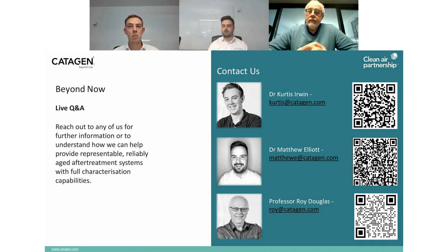So I think the physical emulation and the virtual simulation tool set actually go very, very well hand in hand. And I think we can effectively utilize one digital twin for allowing us to recreate drive cycles, and another digital twin in our Catagen catalyst kinetic model, which effectively is a digital twin of a different nature to predict the catalyst behavior and tailpipe emissions.